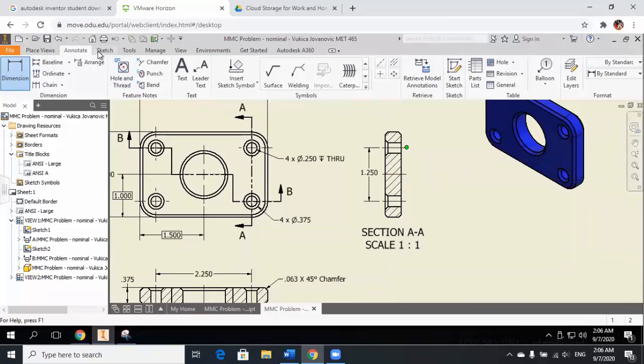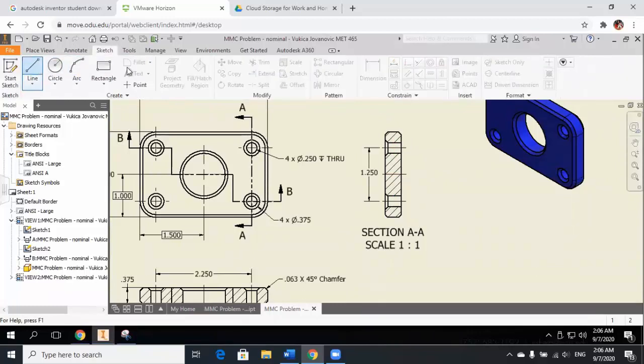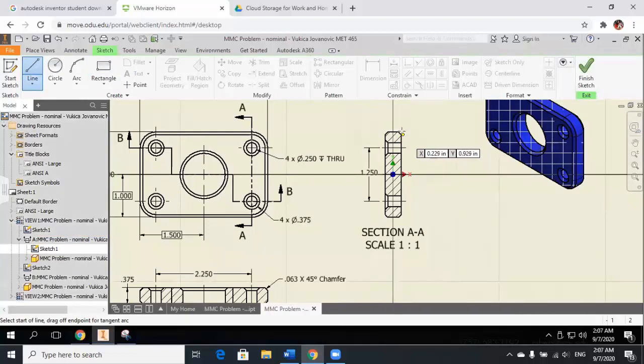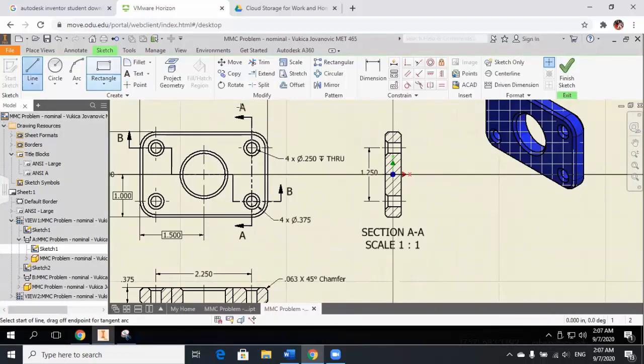And if you want to put it a little bit outside, you will say sketch line, and we'll have to add a line starting, oops, I think I'm a little bit outside, so let me try again. So you see I'm in the sketch, so I will add one starting here, make sure it's vertical, so escape, that's one of them, and I will need another line here, there, for my B reference, escape, and one will be here in the lower part.